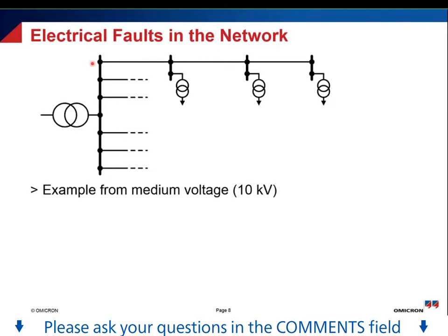And we want to have a look at one feeder, which is a radial feeder. Here you can see we have our main bus bar with the in-feed, and we have small substations on the line that have distribution transformers which supply then the low voltage network. So the customers are connected to these distribution transformers here, here, and here.